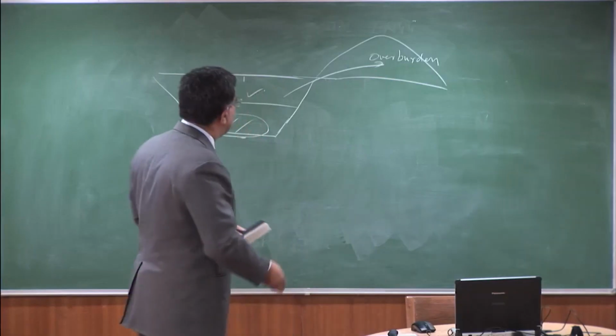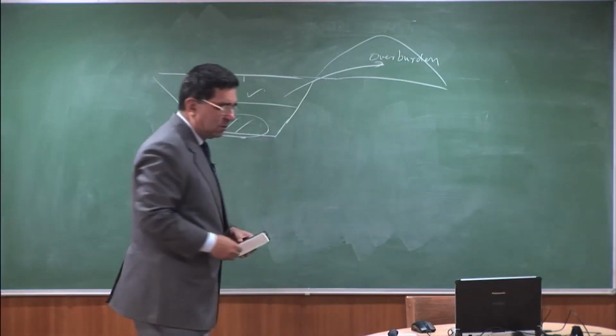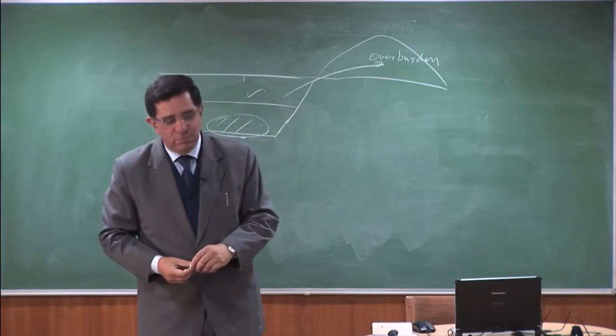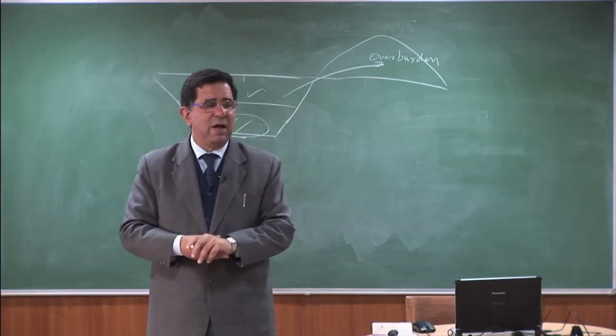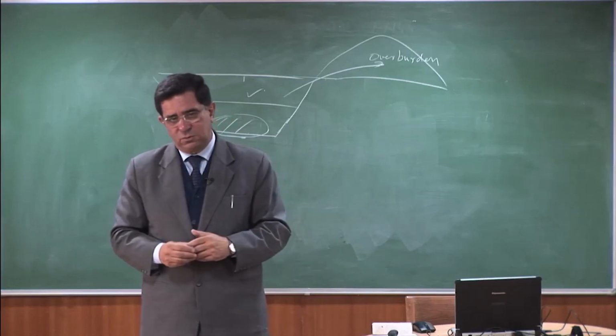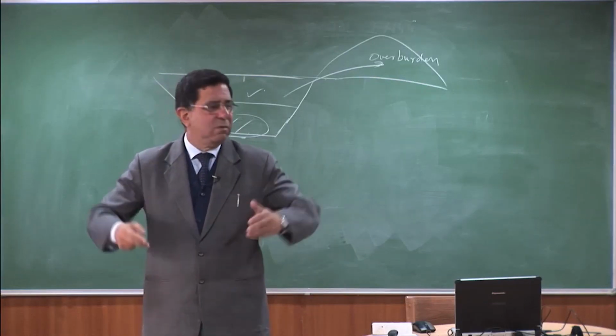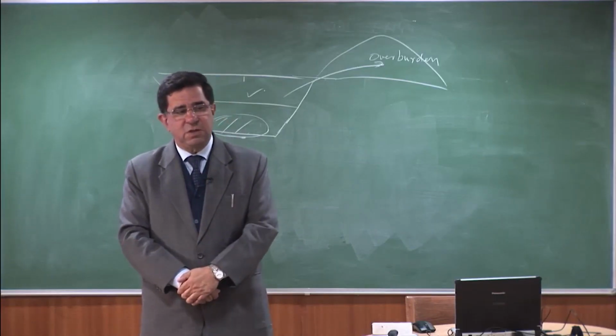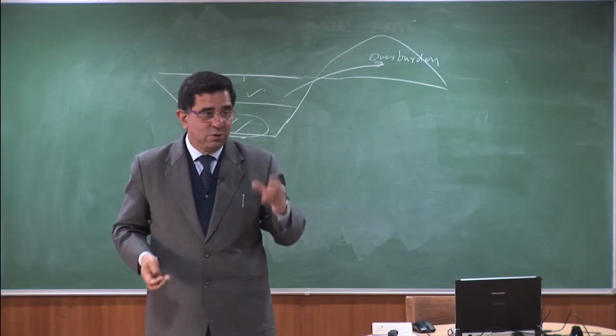Unstable slopes, so we will make them flatter. A slope stability problem, he says when you are going to go 100 meters below, you want to excavate it at 1:1. Firstly, it will be rock, so you can do steep slopes, but if you can't, we can make them flatter.